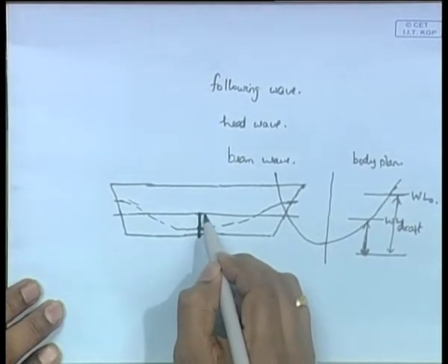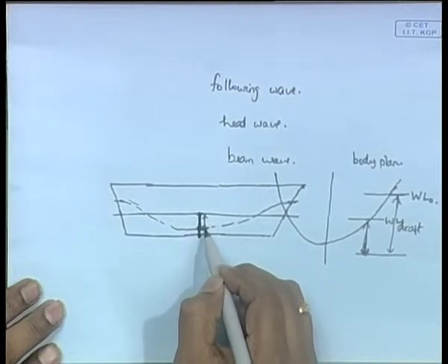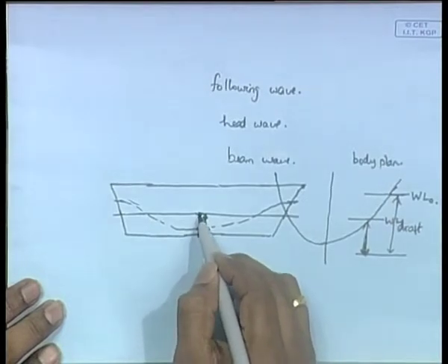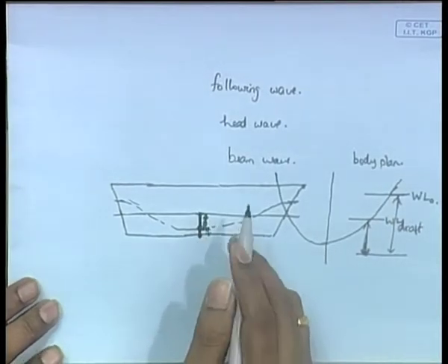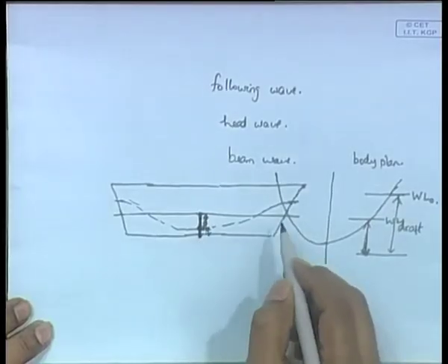This is the water line, therefore this is the draft now, and initially this was the draft. In the midship part, because of the change in draft, there is hardly any change in breadth, because the midship is actually wall sided, it is almost like this.